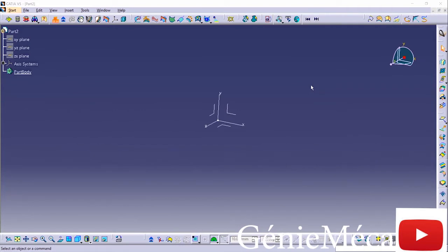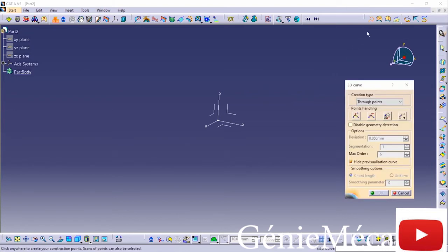In Catia, there are two different types of splines we need to talk about. First is the Generative Shape Design, or GSD spline, which you should already be familiar with. Next is the 3D curve. This is a NURBS type of spline. And there's a couple of creation types we're going to discuss. There's the through points and control points. And with these, if you're not picking any sort of background data, everything that you do select is going to default to what's called a privileged plane.